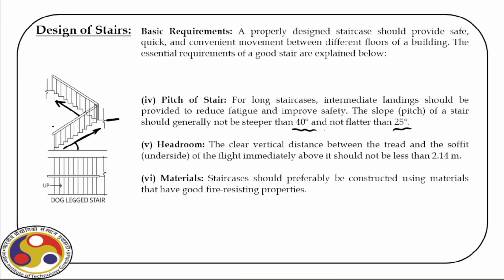Now, headroom is equally important. In a building, if we design, say, a frame, normally for residential buildings, these frame heights are 3 meter. So, this is 3 meter. If we provide a stair within this structure, we can provide a half landing here and then a stair there.